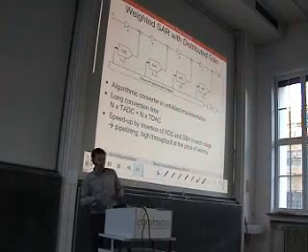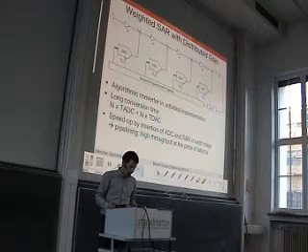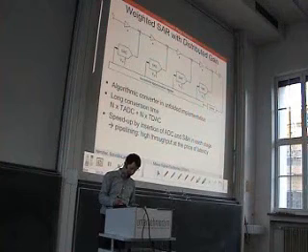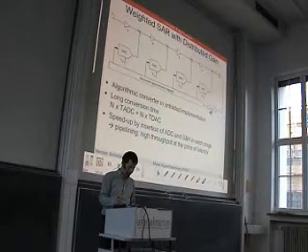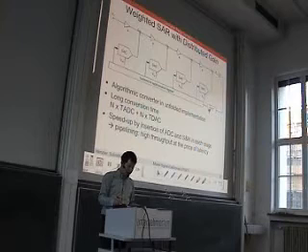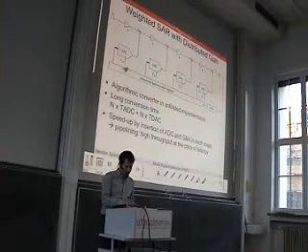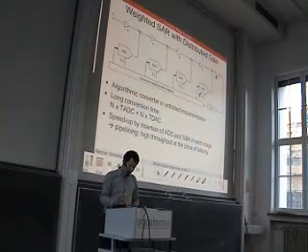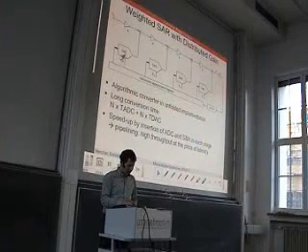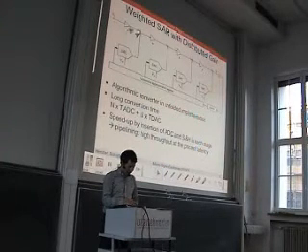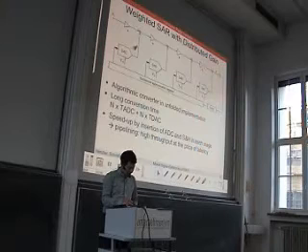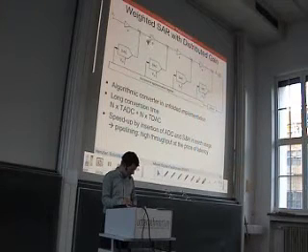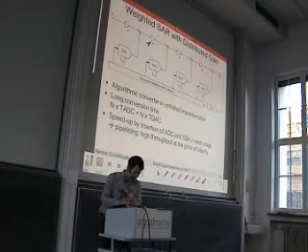Then we tried to translate this into a block diagram, and this was the final slide that we had. We said here there is a control circuit implementing this algorithm, and this control circuit steers these DACs here. So we are starting with the MSB, check here for the sign, then we steer this DAC, subtract the input signal and the DAC value, and we amplify this by this factor of 2, for instance. We can also use another factor, we will see this later on.